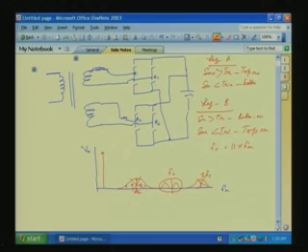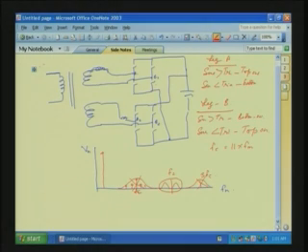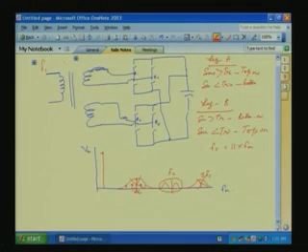Here it may be flowing, but it has opposite effect in the transformer core, and it will not generate any flux, and it will not couple to the transformer primary. So, transformer primary will have the fundamental, then sidebands at 4Fc plus or minus 1 and minus 3, that way it goes. Okay.